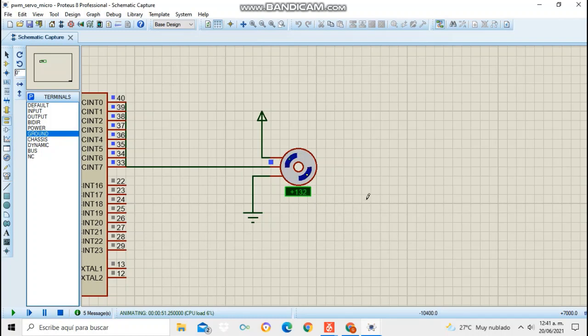And well, here I configured the motor from 180 to 0, and I just configure the PWM so that 10 to 20% is equal to 0 to 180 degrees, and here I just make the calculations to know every position of the servo motor. It's just a proportionality between the two conditions, and here it stops and it starts again. So that's all.